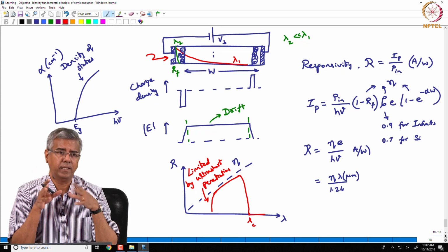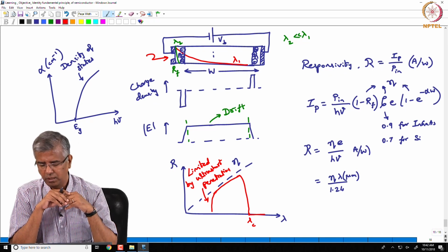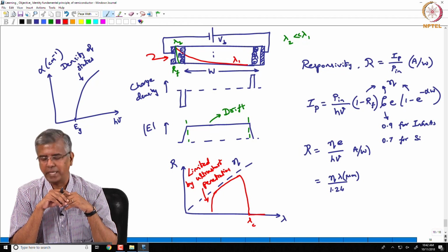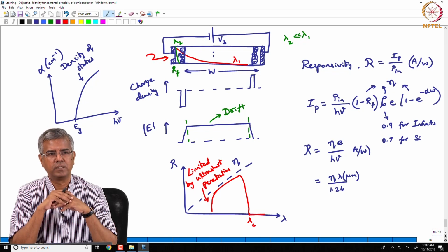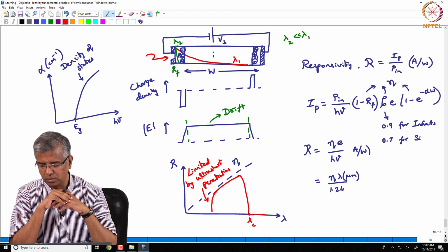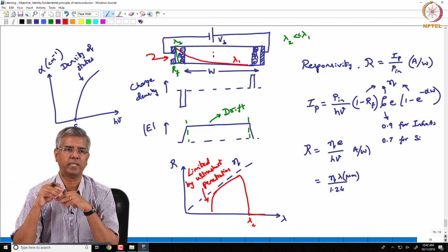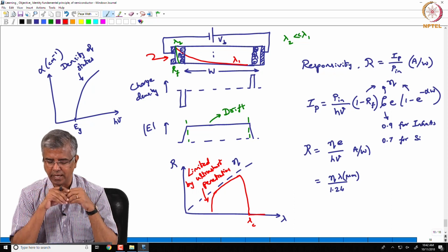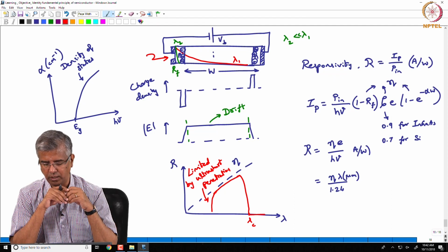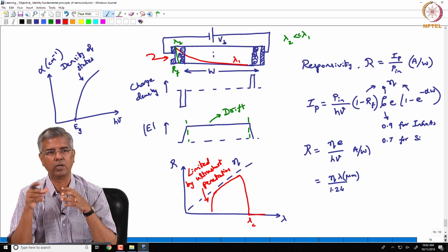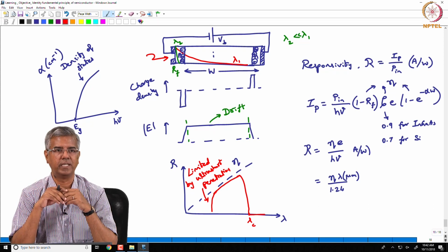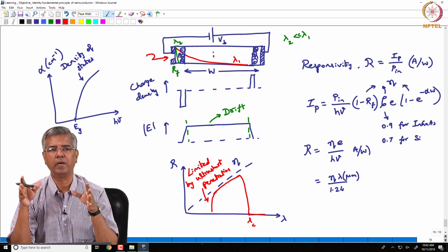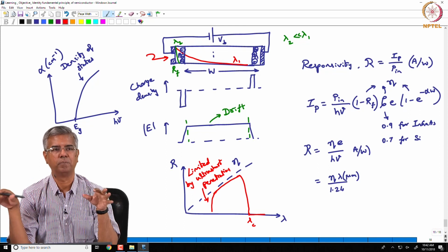Part of it could be, yeah, we're just looking at the first level thing, but if you leave light over there, some of those photons can come back. But you typically design your photodiode for that longest wavelength of operation. So at the longest wavelength, it should be absorbed completely.